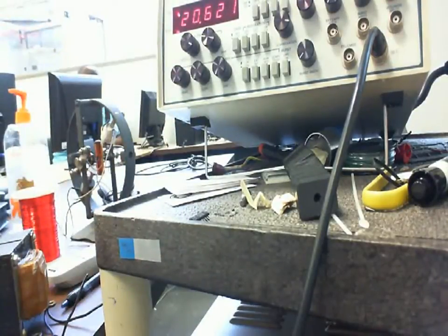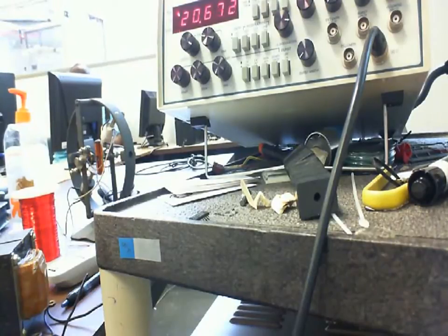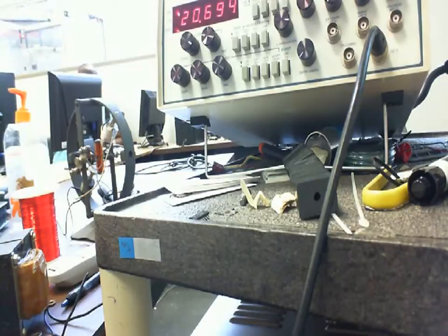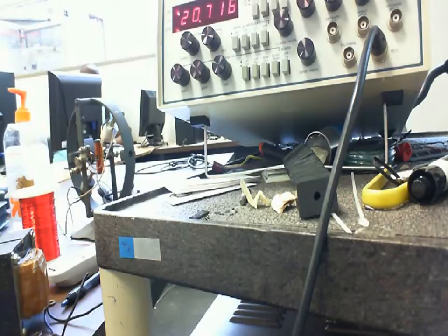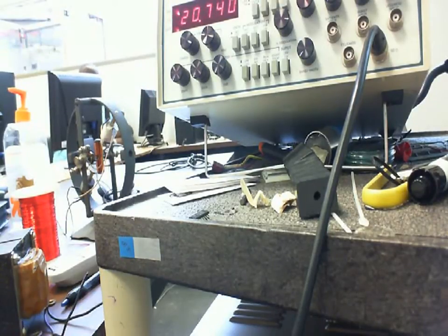So if I'm in a speed critical application and I'm trying to count that thing for 1 minute, my motor speed could have increased quite a bit, and I don't see it until the next what? Into the next minute. But if I updated this thing every second, or every half second, or every third second, I changed the gate, then this thing here would respond instantly.